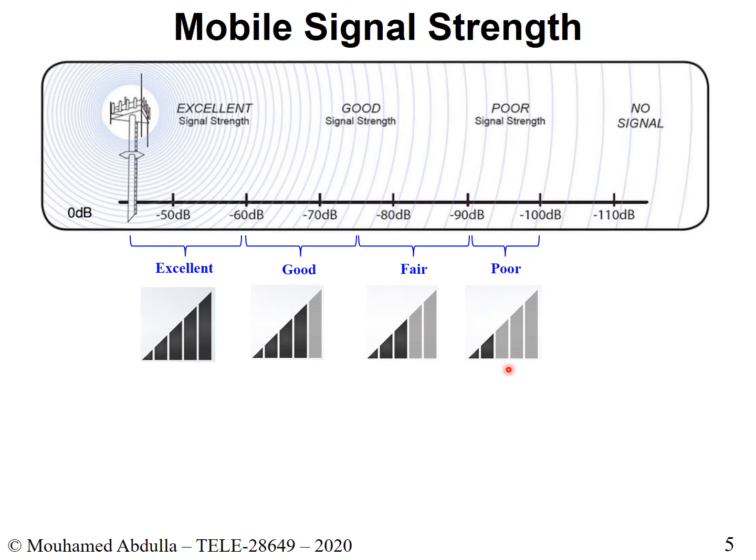And if you have anything below that, so between minus 100 dBm to minus 110 dBm, well, now your signal is very weak. And in fact, to visualize it to customers and to people looking at their phone, you'll probably see only 1 bar on your phone. Okay, and if you go below minus 110 dBm, it will be completely an outage. So you won't get any signal.